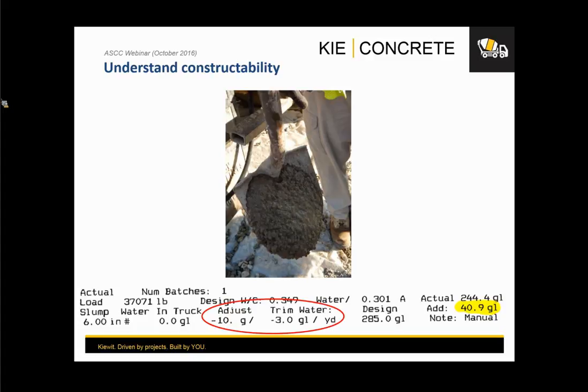Basically, because of the low water content that mix was coming from the batch plant. Now this mix was not even coming out of the shovel. It was sticky, right? It was not even falling off the shovel, right? So those are things that are simple to modify, right? If the concrete producer has the right controls in place to monitor moisture contents of the aggregates, and they are on top of it, make sure that they have the right numbers and they have things under calibration, there should not be any reason to go to those excessive numbers of trim water.